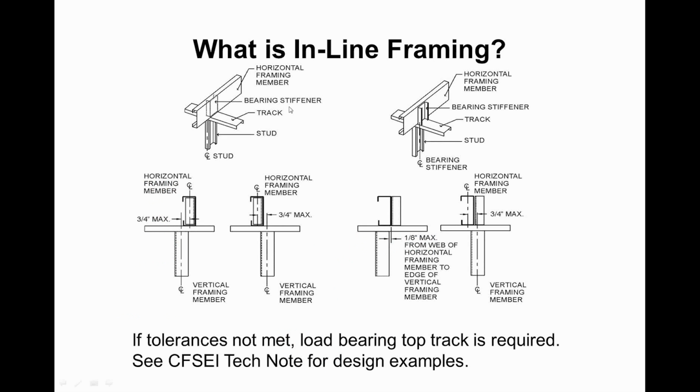So what is inline framing? What we're trying to accomplish with inline framing, first of all, let me back up. As a structural engineer, what I'm trying to do with my structural assembly is create a skeleton for the building. This skeleton is to transfer the load. For example, if I've got my floor load on this joist member, this joist then will transfer that load to this location at the support. Transfer it then to the stud moves it down.